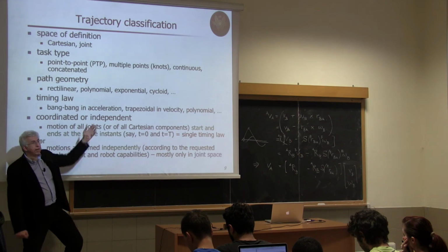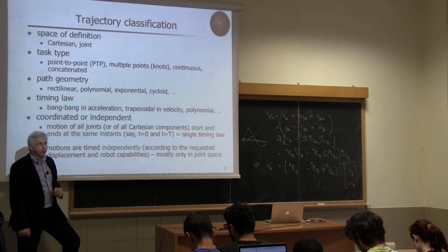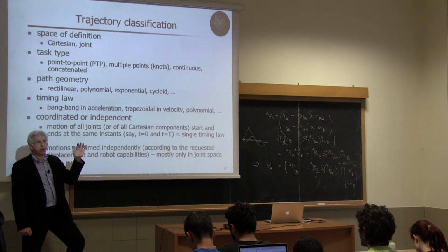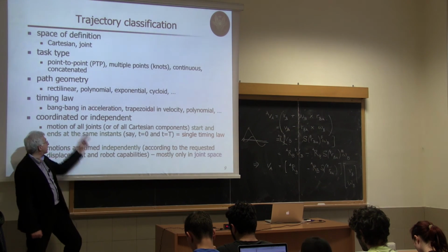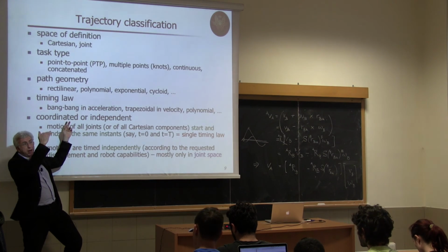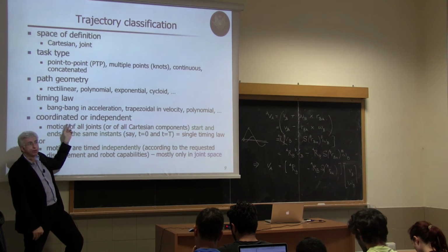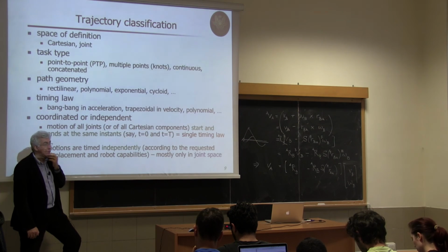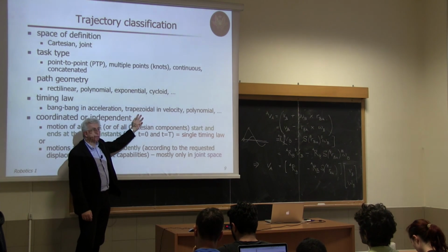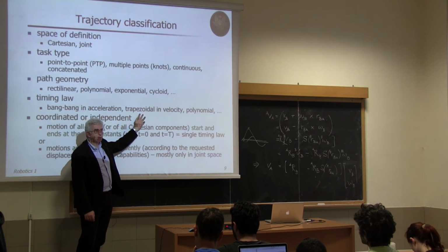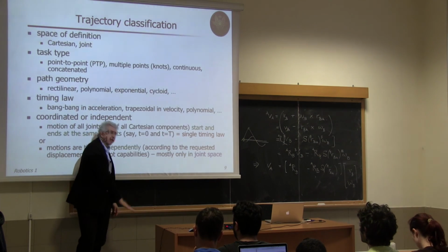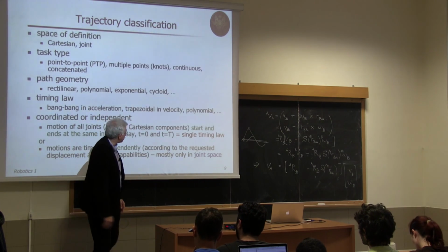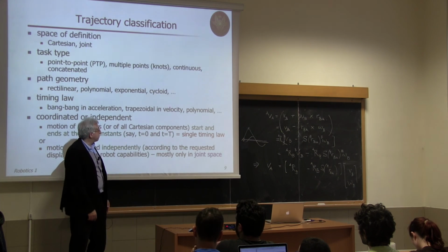Or you may eliminate the cruising part, so you just increase velocity linearly, reach a peak, and then decrease it to 0, which means that the acceleration is maximum positive and then maximum negative, so it's a bang-bang acceleration. This profile is also called bang-coast-bang in acceleration, because when the cruise velocity is constant, the acceleration is 0, so you go from maximum acceleration, to 0 acceleration, to minimum acceleration, or maximum deceleration if you wish.